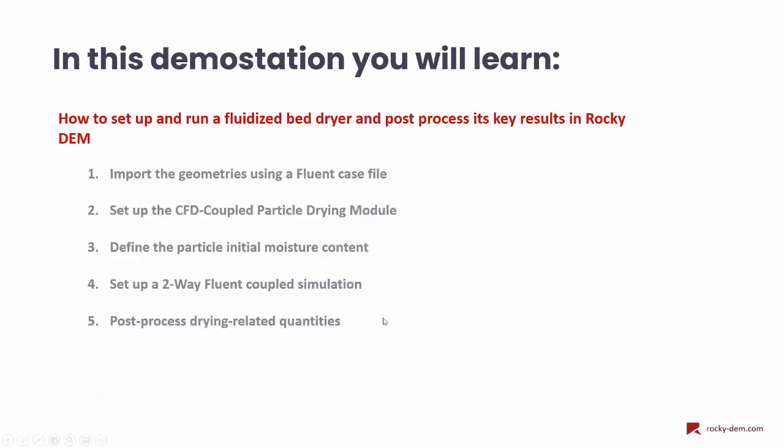So in today's session, we will be setting up a very simplified fluidized bed dryer, and then we will be post-processing it. And this is what you will basically learn today. You will learn how to import geometries using a Fluent case file, which is a very nice feature that Rocky has when you are doing CFD coupled simulations, instead of loading STL or any other supported file types.